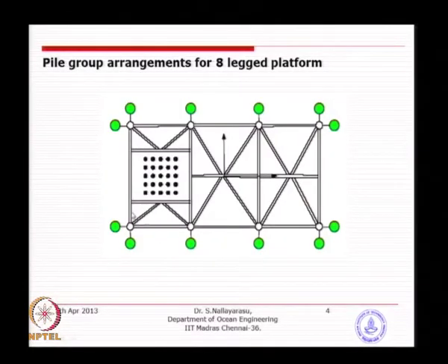So you can see here in this case it produces larger spacing because there is no main pile, but only skirt pile. You can see here the distance has increased reasonably, and in other places you have only single pile. So between this and this definitely will not be a problem because it will already be very large spacing. So the problem will be mostly associated with too many piles at one particular corner, and that is something that we need to look at.